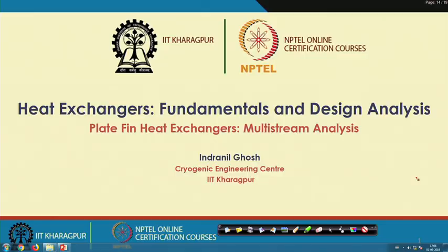Welcome to this lecture. We are going to talk about the plate fin type heat exchangers, and we were discussing the analysis of plate fin type heat exchangers, where we have analyzed the fin equation and we tried to differentiate between the different temperature domains or the temperature configurations that are possible in a plate fin type multi-stream exchanger.